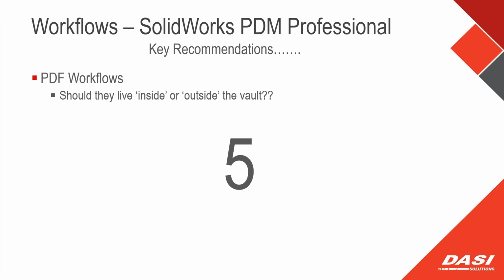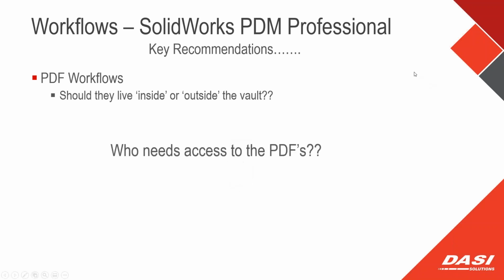The way that work happens these days, PDFs very much are for end users. I just call them a customer, but that customer could be somebody in the building, the manufacturing individuals, or sales, or anybody really. But what we need to decide up front here is whether those PDFs, produced from any of your CAD documents or Office documents, need to live inside the vault or not. Now, the mechanism with SolidWorks here is that we use tasks for this, but we need to know who needs to access the PDFs.